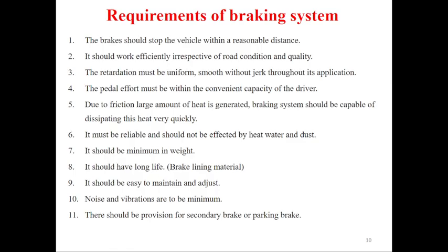Then the requirements of the braking system. The brake should stop the vehicle within a reasonable distance. It should work efficiently irrespective of the road conditions and quality. The retardation must be uniform.